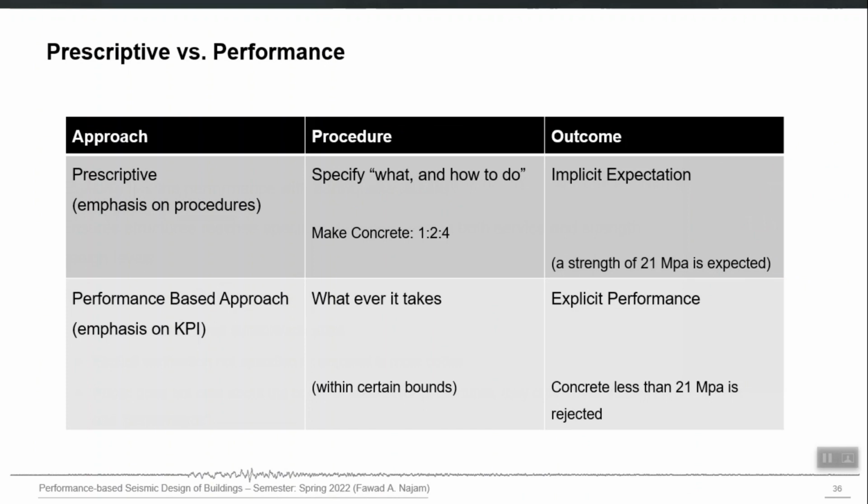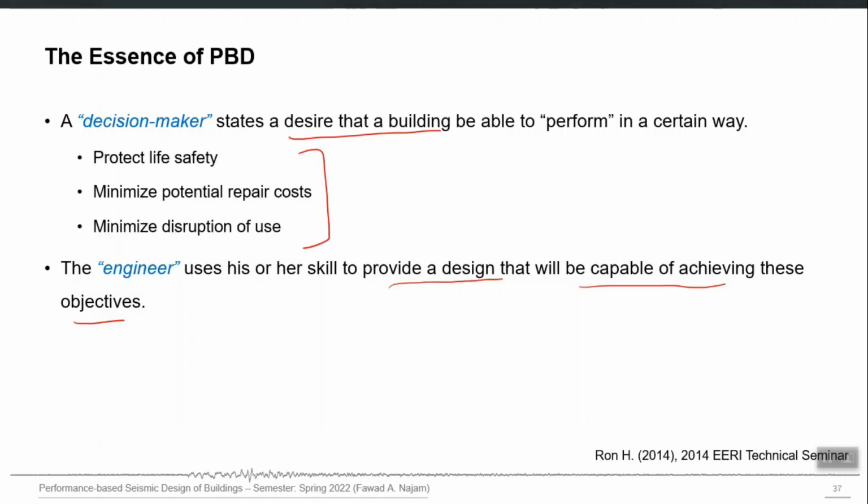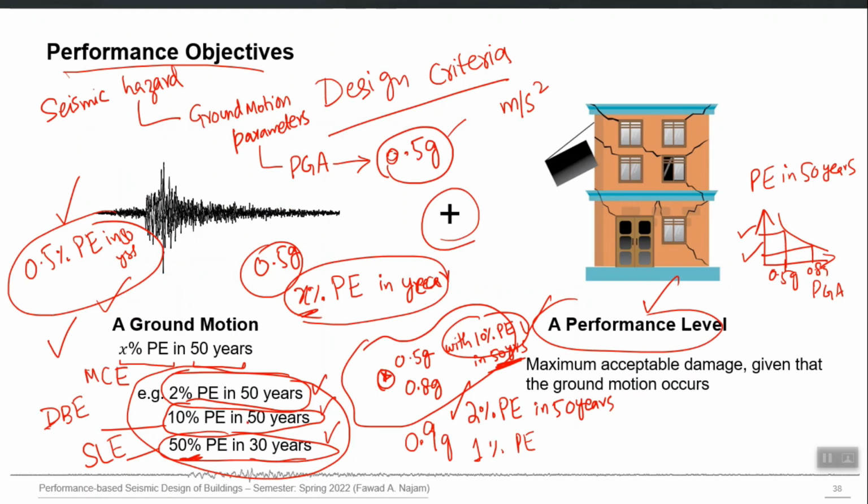And there are standard specifications and guidelines of PBD which guide us on what probability of exceedance we should use for different purposes. For example, as I have explained, this 10% probability of exceedance in 50 years is a standard definition at which buildings should be designed, right. So the conventional building codes also, when they report the hazard map, report on this probability of exceedance.